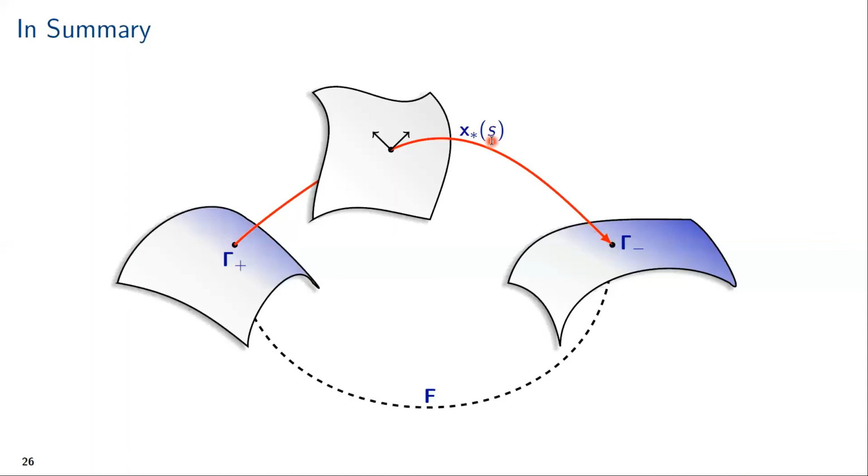Now, when we found such a trajectory, this approach also showed that we could easily define a natural set of so-called transverse coordinates if we could find a projection operator to recover the variable s. That is, these transverse coordinates have their origin on the nominal trajectory, but are non-zero away from it, such that if we stabilize their origin at all points along the trajectory, then we naturally also stabilize the periodic solution in the so-called orbital sense as well. So we have this nice combination of an approach which both lets us plan a trajectory and then in a sense also gives us a way to design a controller as well.